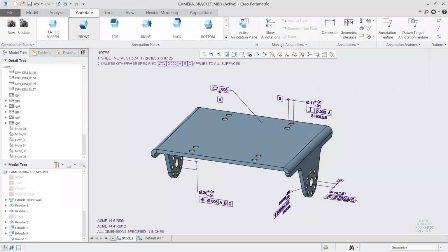In our case, where we went through the example of Creo identifying that we had a 0 tolerance, that was just because Creo recognized that that's something that has to have a tolerance. You can actually override that and just say, I want to leave it as is and not include that, but it doesn't always have to be the case. Creo's not forcing you to put in any information.